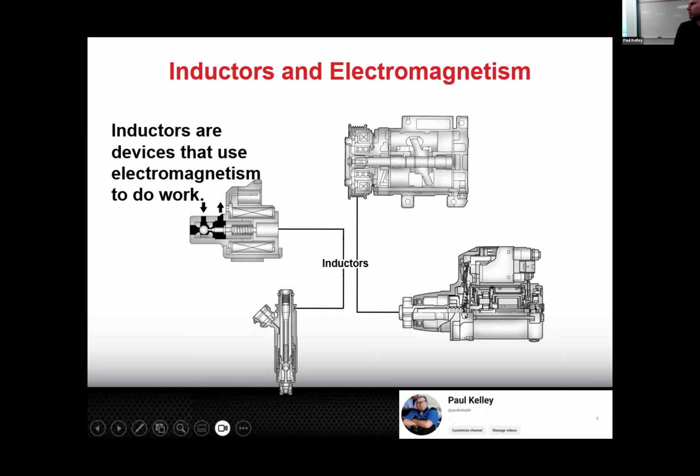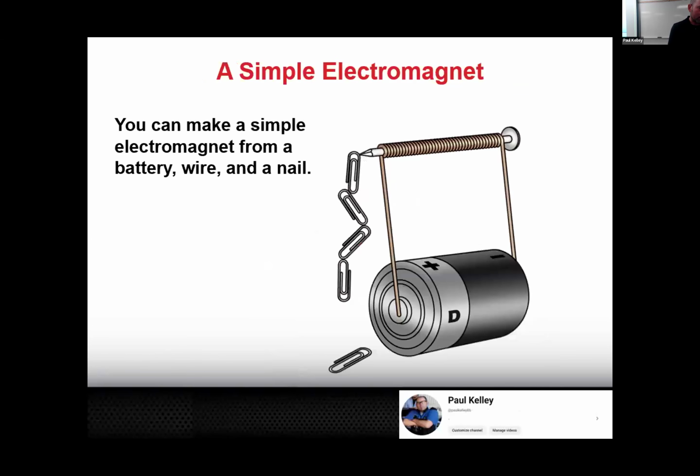What's the difference between that and a motor then? A motor is going to have a mechanism where it switches over and over and over, right? With just a solenoid, we only move it one way and then we release it. With a motor, we give it 12 volts and ground, and then a mechanism inside switches 12 volts and ground to ground and 12 volts, and it continues to move it in a rotation, right? So that's kind of the overall of what that looks like.